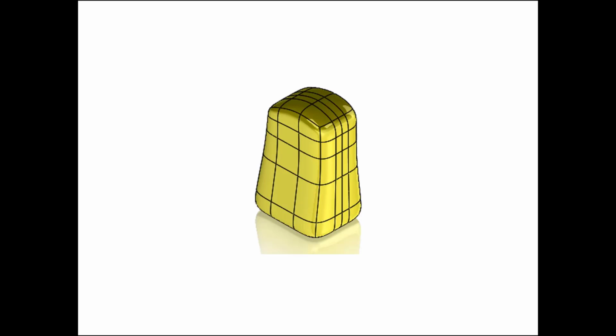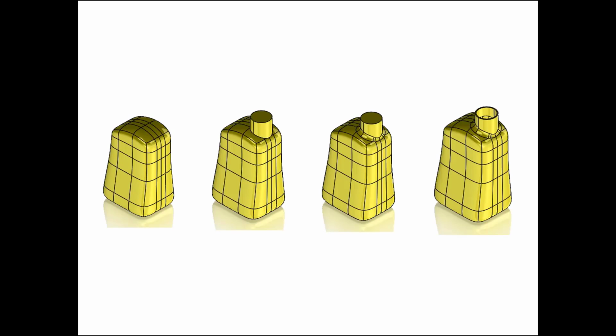xShape is great for sculpting organic shapes from primitive sub-D surfaces, using the many available shaping tools and techniques. But in some cases, that is not enough to complete the physical product. The addition of more common modeling tools is often required. This is where the xDesign tools come into play. Extrusions, revolves, fillets, and chamfers can be used to add the more prismatic shapes required to complete the job.